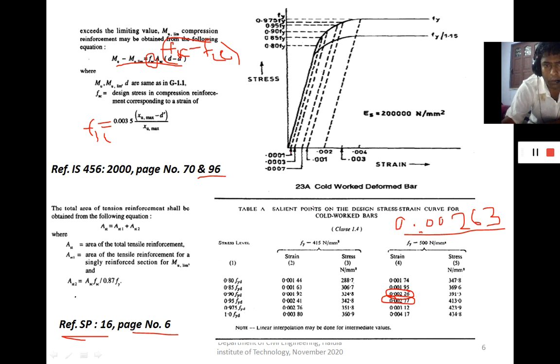So better you use this SP16 table to get the stress value for the corresponding strain. The interpolation is made.